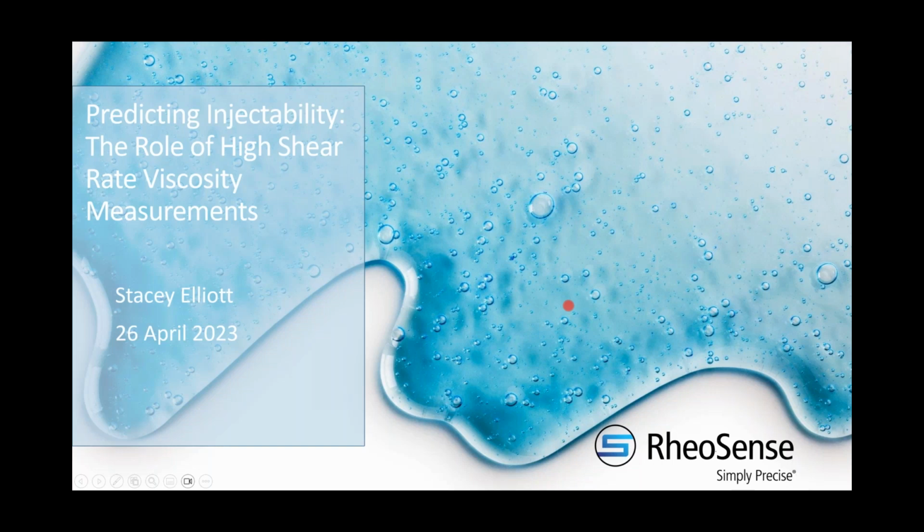So these are all the parameters that we're going to need to figure out how to deal with so that we can predict our injection force. We're going to need to figure out how to incorporate properly the viscosity, the geometry, this pressure drop, and then the volumetric flow rate. So that's the goal of the next few slides, to really figure out how we are going to get a handle on this fluid flow through the syringe.